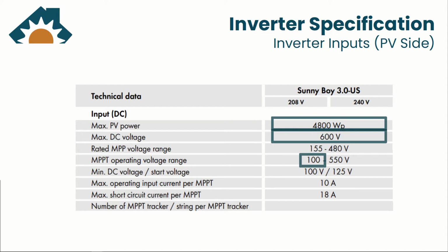Okay, hopefully that wasn't too confusing. All right, so you can use any of these. Any lower than this, the inverter might not power up or be used as efficiently. Last is the maximum short circuit current. Again, connecting more than this could lead to damage that is often not covered under warranty. So no good.